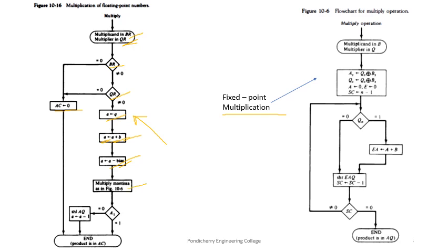So this is according to the earlier step. This is the 10.6 figure, right? This is actually the same procedure we follow here to multiply the mantissa part. As far as the mantissa multiplication is concerned, it's the exact procedure we have followed for the fixed point number case. Then after the mantissa multiplication, there is a check done here. The most significant bit of the accumulator content, that is the product mantissa's most significant bit, is checked for whether it is a 1 or 0.